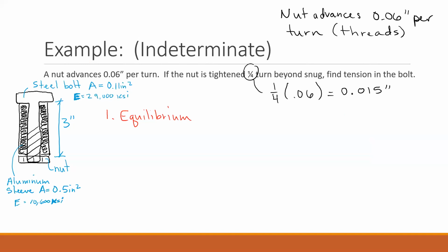In order for the nut to advance higher on the bolt, one option is this bolt could be pulled in tension downward, right? If this shell is not going to give, that means that the bolt is actually being pulled downward with the rigid shell remaining around it.